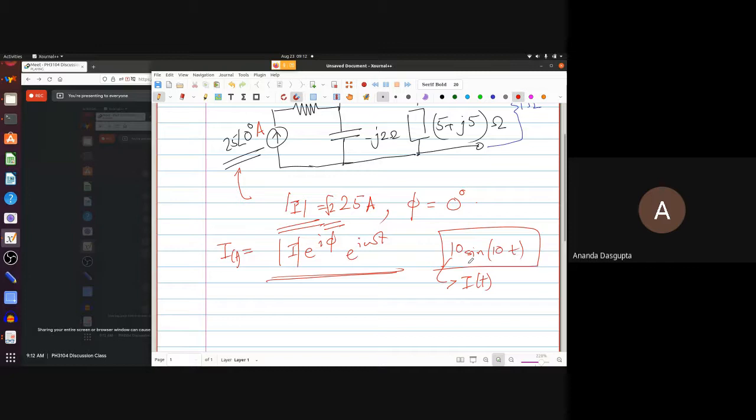Unless otherwise mentioned, when you say 220 volts is your mains, you do not mean 220 volts is the amplitude or the average value. There is no average value; the AC mains should have a zero average value. The 220 volts is the RMS value. That means the peak value of your mains voltage is 220 times root 2. That's always the convention, so there's always an extra factor of root 2 to worry about.